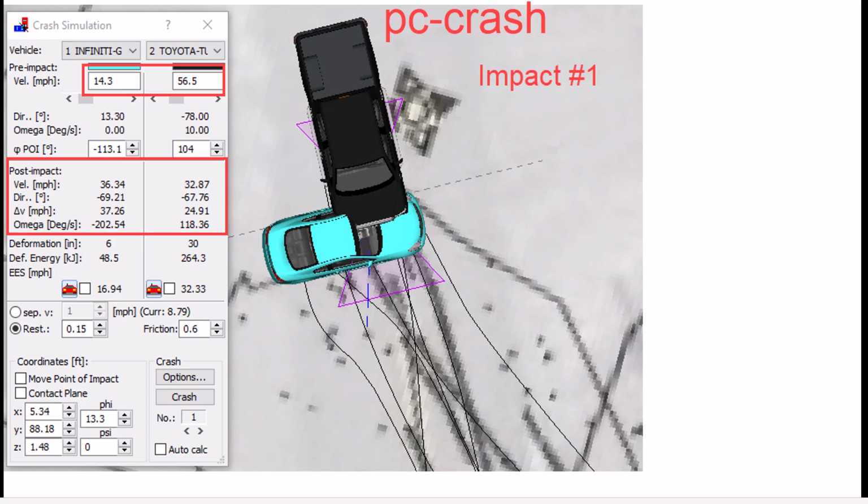a difference. Now, some of the things that you can present or use for comparison is when you're looking at the PC Crash, the Delta V, the impact configuration. In PC Crash or Virtual Crash, because they're instantaneous momentum exchange, they have to start the vehicles at maximum engagement, which if they were showing the actual damage, we'd see whether or not the puzzle pieces fit.